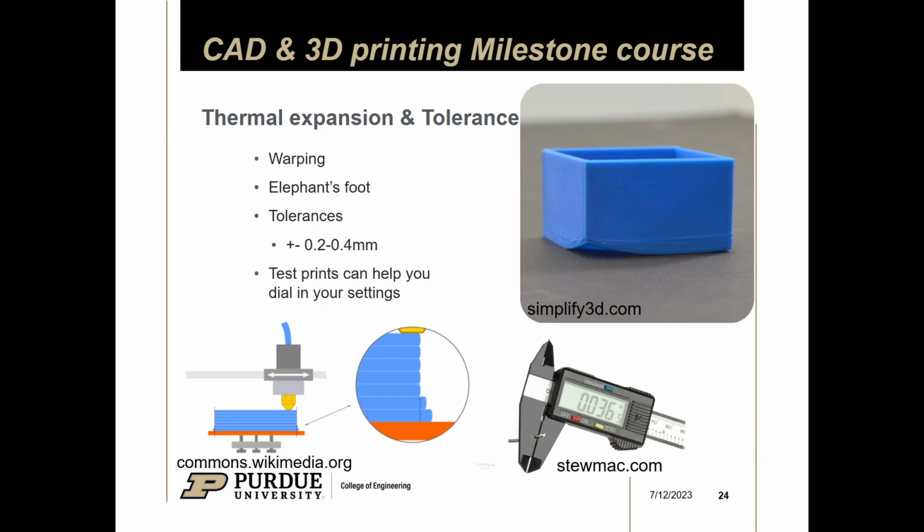Sometimes that's not good because you might want this to be exactly this amount. And if you're trying to make these fit together, there's extra material in the way, right? So one of the things I like to do is chamfer almost every bottom surface that's connected to the 3D printer. If you add a chamfer, it cuts in at 45 degrees. Again, it's a 45-degree overhang, so it's not an issue for the printer. And then any elephant's foot that happens will get squished out into that extra space that you just gave.